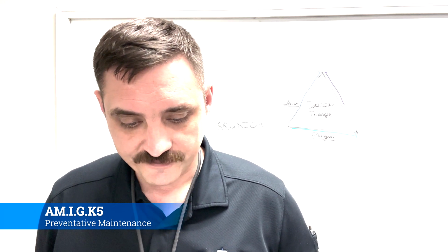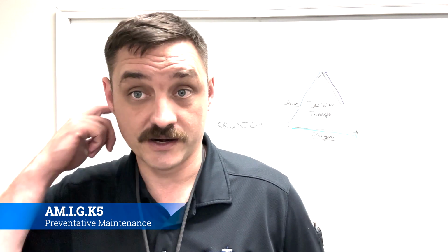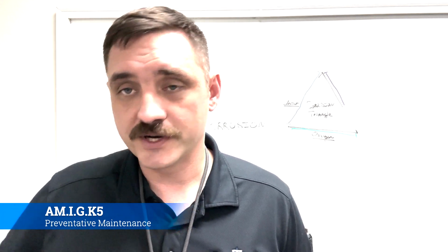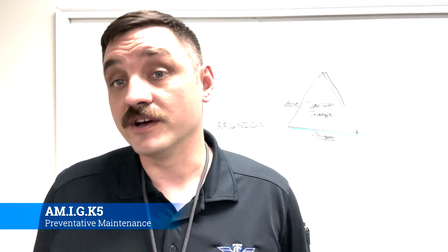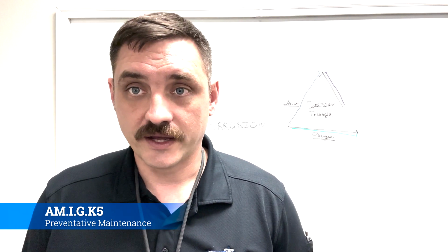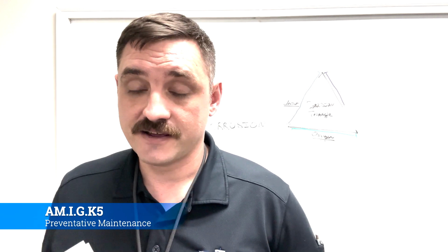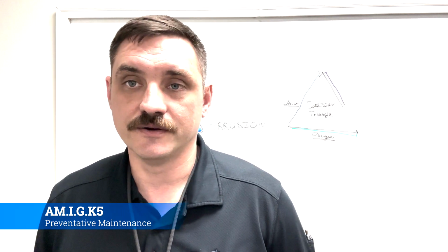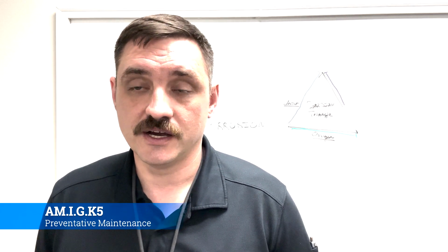Okay. And then finally, maximum use of protective covers on parked aircraft. So put the flyaway gear on. If the aircraft is parked, pitot covers come on, engine inlet covers go on, drape over the windshield windscreen cover. If you have any of that stuff, use it. If you don't have it, buy it. So that way it's a little bit of cost and expense and hassle up front that could save a big cost and a big expense and a completely derailing hassle on the back end. But that's preventive measures for corrosion.